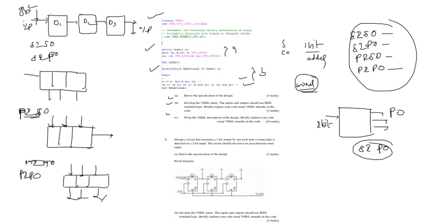So based on this, we have taken this particular diagram. As a 3-bit is mentioned here, we have chosen 3 D flip-flops. This is the D1, this is the D2, this is the D3, 3 D flip-flops. The data input is 1 bit of information here, and we are extracting parallel data from Q0, Q1, Q2. At the same time, an asynchronous reset signal is added here.